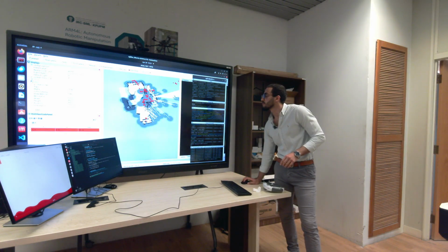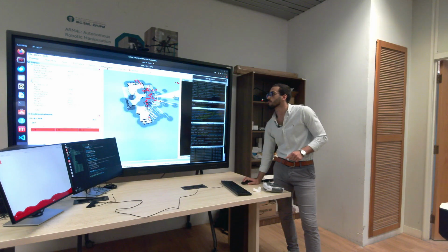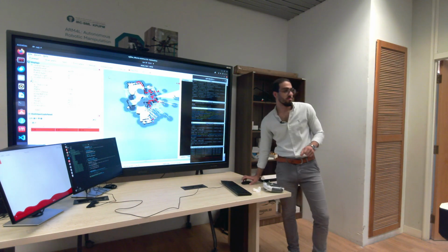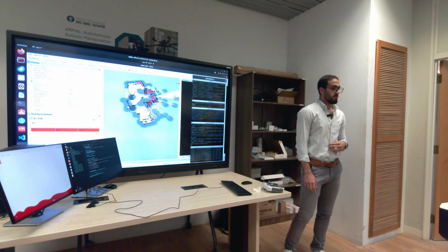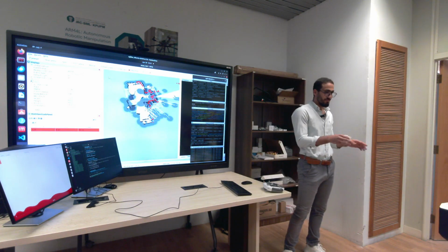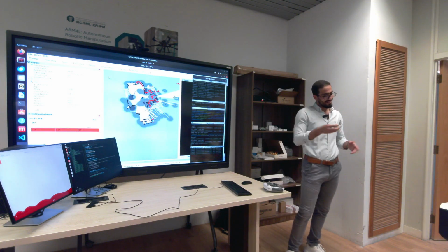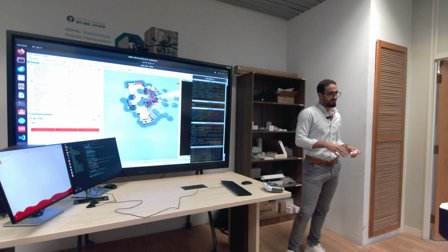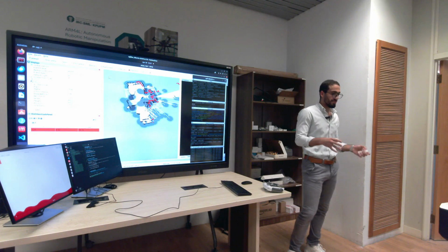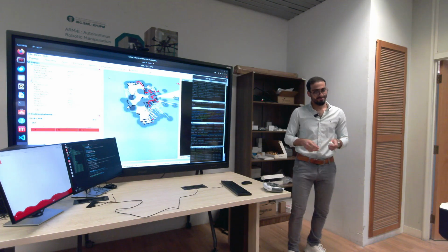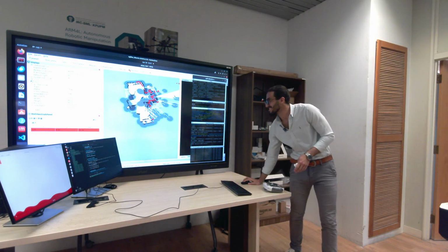Could we ask why this specific camera? Because we have one. Oh, can you say something about the camera? It's called depth camera, right? There's depth camera, yeah. Not just the camera. RGBD, yeah. But what else? We can make a SLAM. We can make this simultaneous localization and mapping with the camera itself, with only the camera. But today we are making it with the LiDAR. And in the end, hopefully, we can integrate them. At the end of today, I will show you a picture that integrates both the camera and the LiDAR as well. But I hope this error does not come in again.